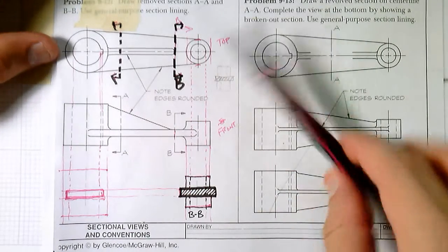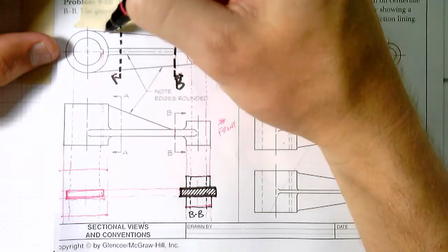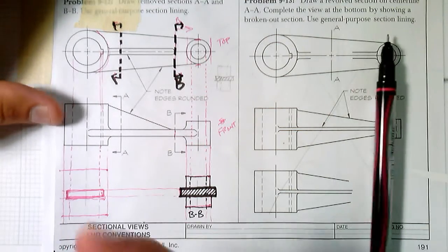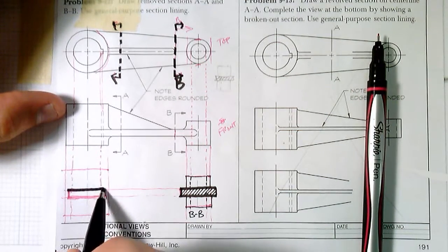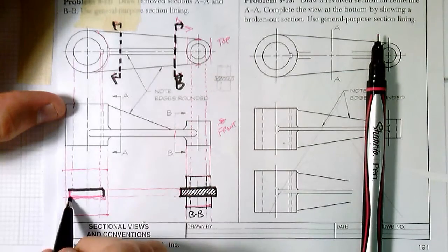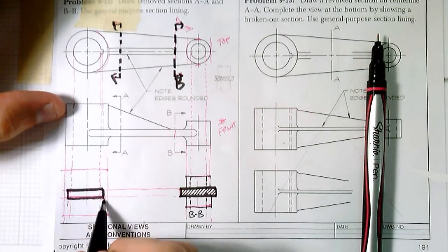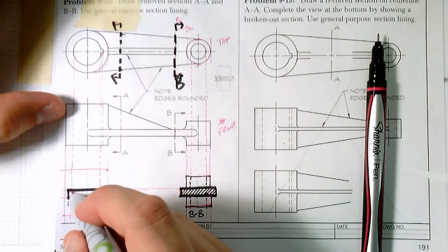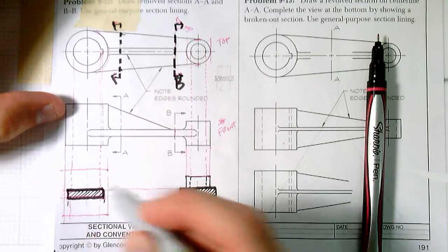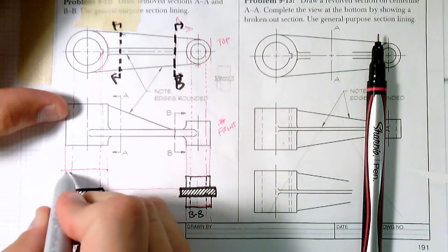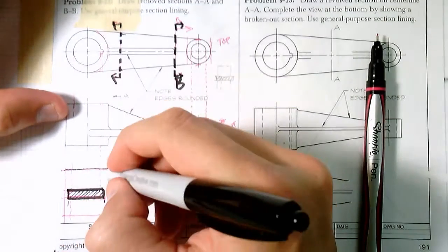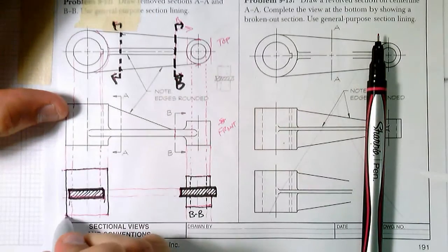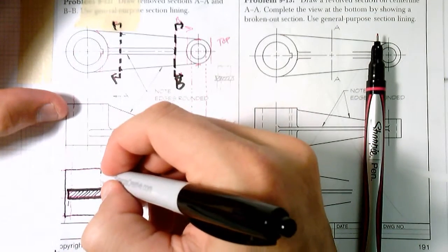And now we'll just darken what's being cut because we're looking at that side view. All we're drawing is the material we're cutting here and the face of that object there. So I'm going to darken in the outside. Now remember, that length right here is this length right there. Do our hatching. And then I'll create my outline. And I'll make my hidden lines.